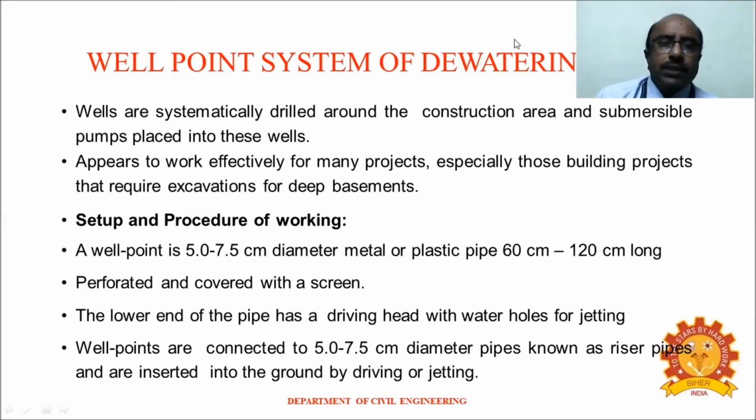The next method is the well point system for dewatering. This is also a widely used method for reducing the groundwater table. Wells are systematically drilled around the construction area and a submersible pump is placed into the well.